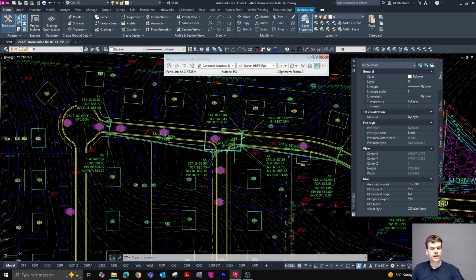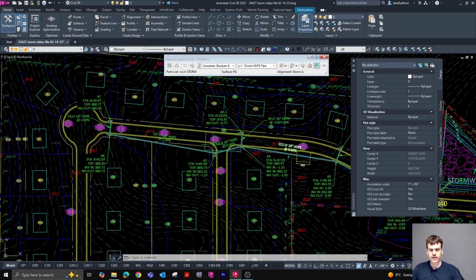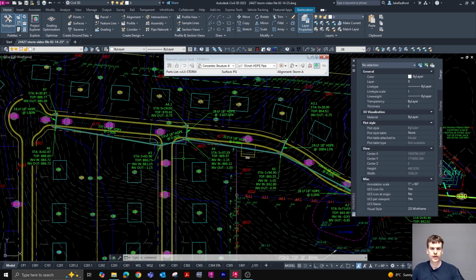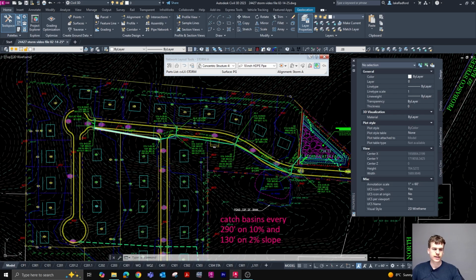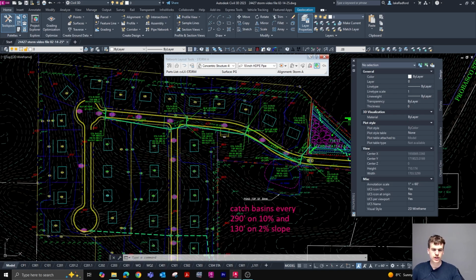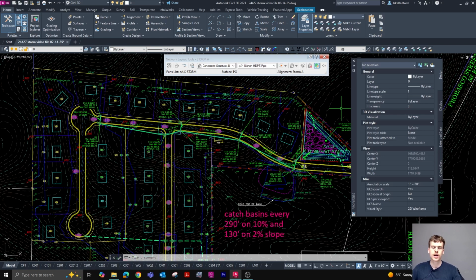And you can continue this process all the way throughout the entire pipe network. But one thing that's key to know is that as civil engineers, we always design from our constraints. So typically, instead of designing from the most upstream point all the way down, you'll probably do that exact same process from the downstream point to upstream. As a general rule, we're always working upstream to downstream. I just wanted to demonstrate that sort of negative slope dynamic that goes on when changing slopes from upstream to downstream, which you may do under certain circumstances.